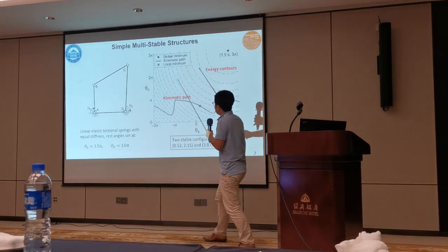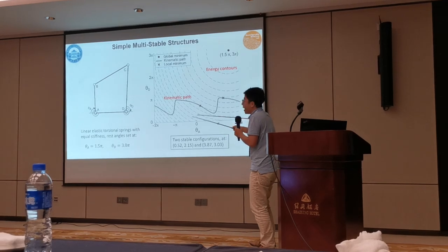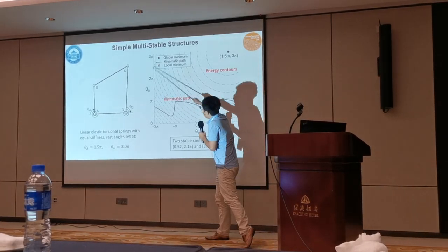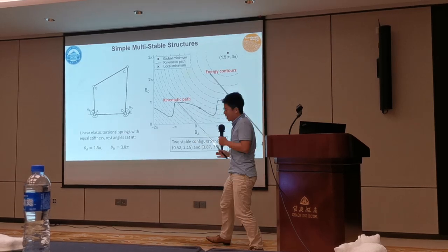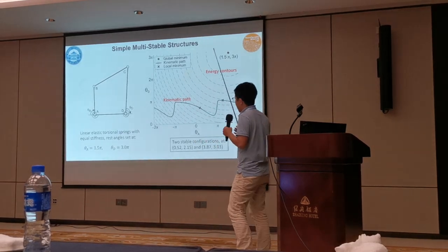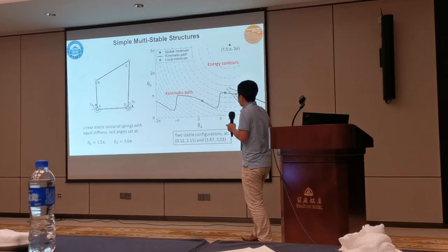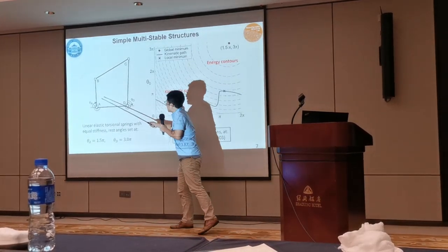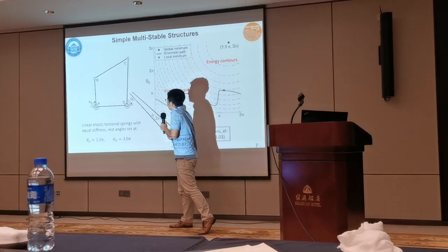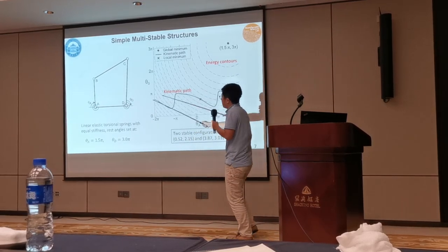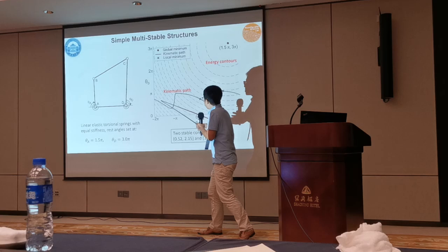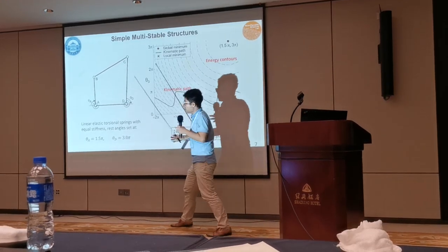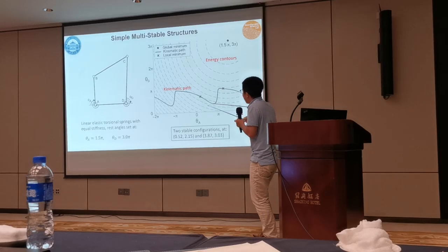Another thing is that we plot it in this space. The X-axis is theta A, and this is theta D, and these 2 parameters are sufficient to reflect the kinematic path, right? That's the mechanism, because they are not free. They're mounted, because it's a 1 degree of freedom. If they don't satisfy this relationship, the 4-bar linkage will just break apart. So that's one relationship we have, but also the energy, right? These 2 springs are also sufficiently described by this plot.